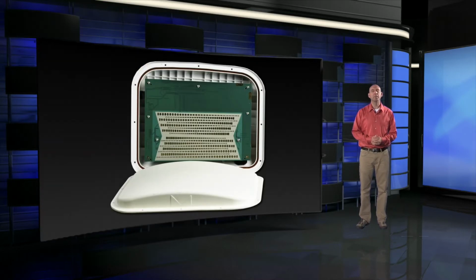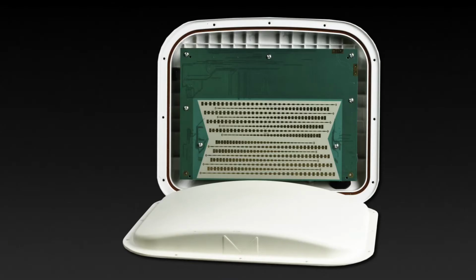This next image that I wanted to show you is a picture of SmartSensor Matrix with the lid removed. I wanted to show this because this was my piece of the development project. I designed these 16 different antennas so that each one is steered to a slightly different angle. And as you can see, each of the rows of rectangles is a separate antenna.